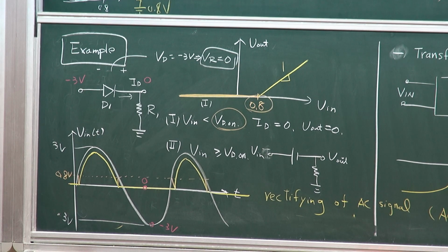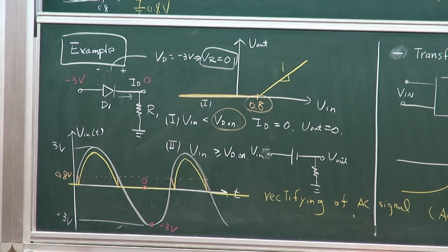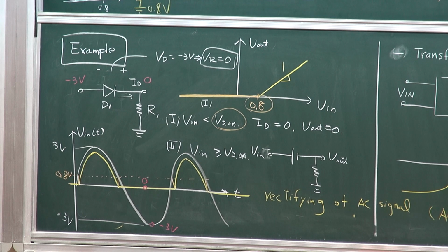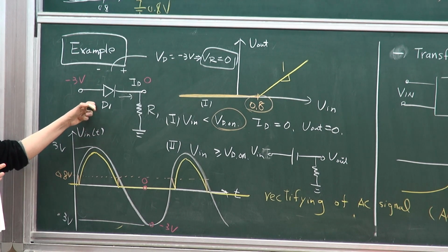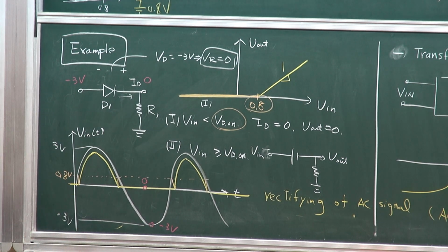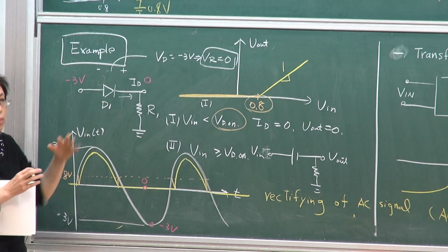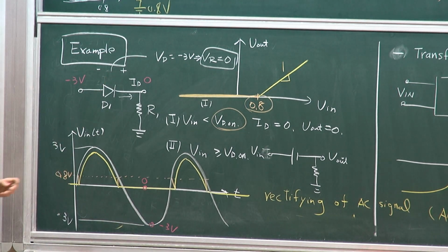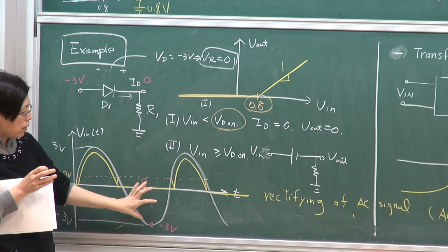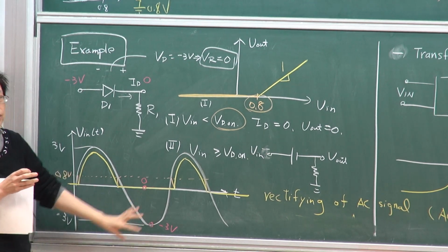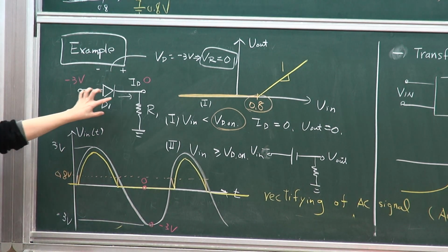So the diode, as I said in the discussion of breakdown, is where it counts to sustain voltage. If I'm giving you a pulse of like 1,000, you should be able to sustain 1,000 when it's off. You want to make sure that it's off. Otherwise, it will not be rectified. See, there's a voltage difference. The negative voltage is being dropped on the diode.